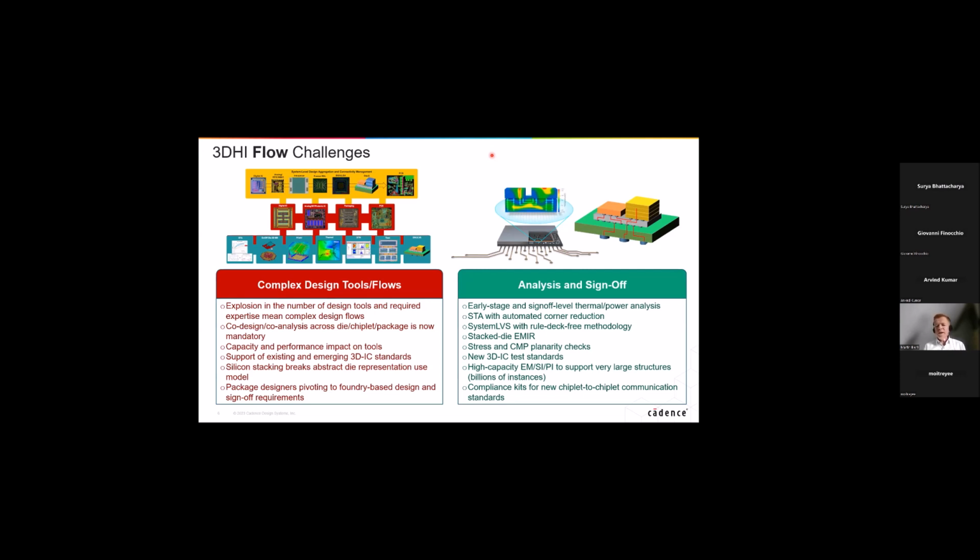Timing analysis on the whole system, especially system LVS, to make sure that the net list you have through all the fabrics through the system is correct. That's also a big challenge. Electromigration of stacked dies, stress test, warpage is also a big topic in these kind of chiplet and stacked dies.